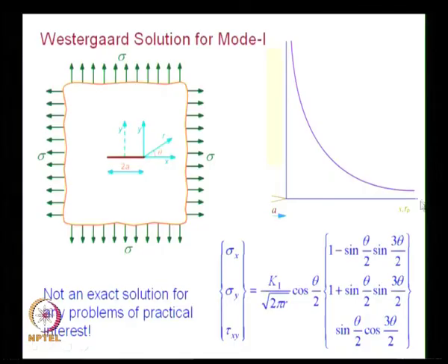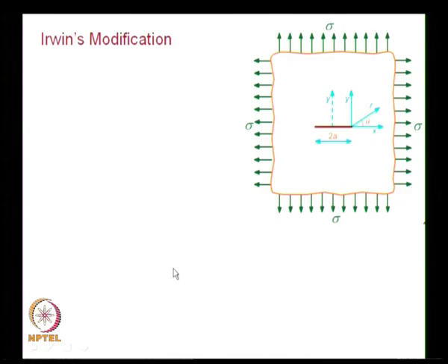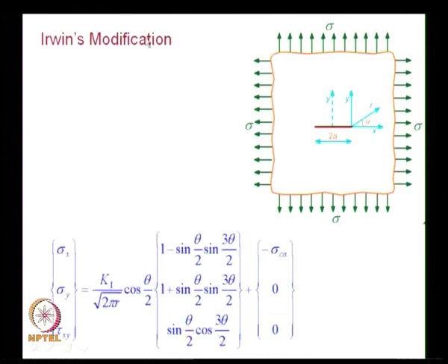If you really make the fundamental question, what happens when r tends to infinity, this solution says only 0. So, what you will have to keep in mind is this is a near field equation. If you understand that this is near field, not a closed form expression, then using this in an uniaxial situation is also reasonably okay. But people have made certain observations which are quite not right.